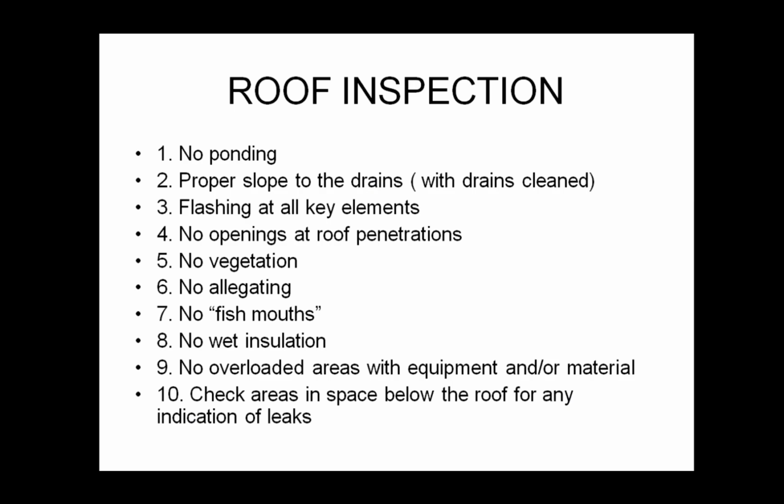But again, depending on the roofing type, some are more able to withstand things like ponding. It could just mean that it was a poor application, and that water will go away when it gets hot and the sun hits the roof, and won't be a problem. But if you have severe ponding, there's an issue. That can also add weight in a localized area, and that could be the first area of structural failure if you have an extensive amount of ponding.